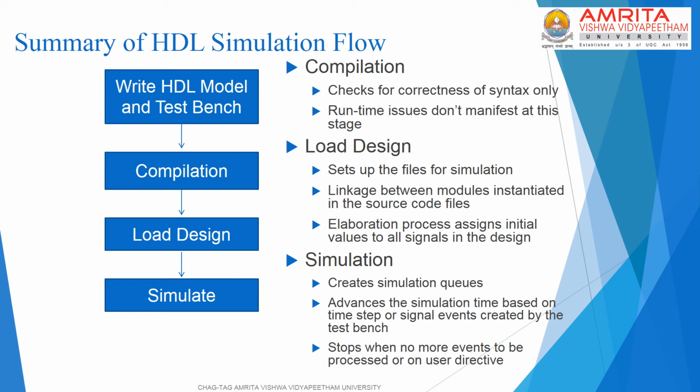The next step is the simulation itself, where the simulator creates the simulation queues using the delta cycle computation, which was illustrated in the previous slide. The simulation time is advanced based on the events in the different signals as assigned in the test bench.